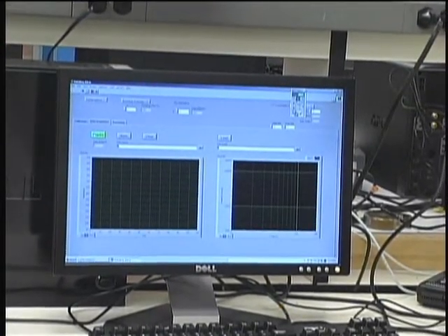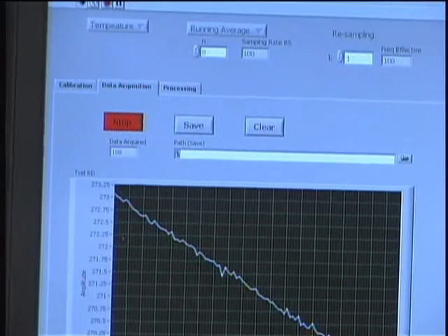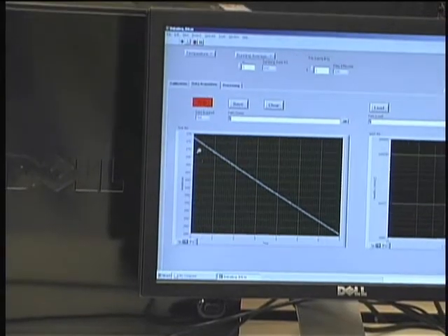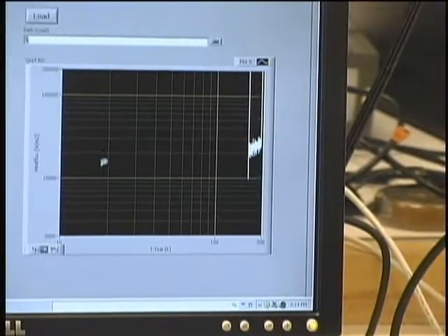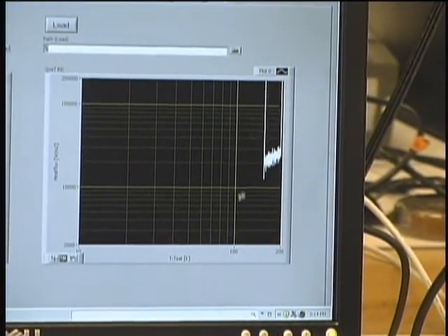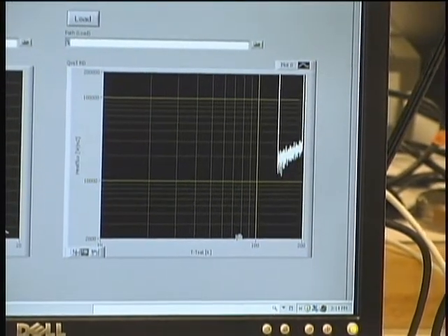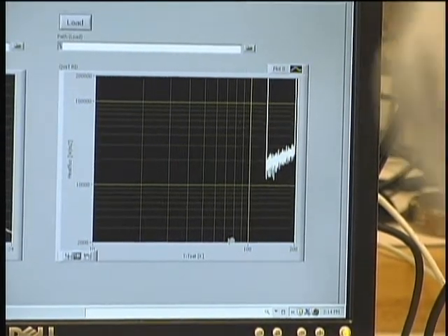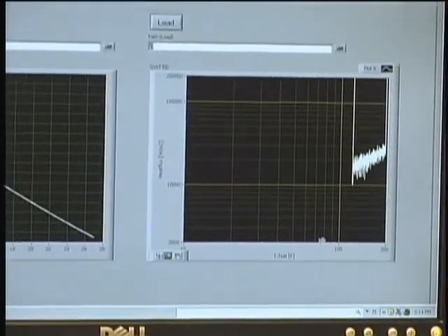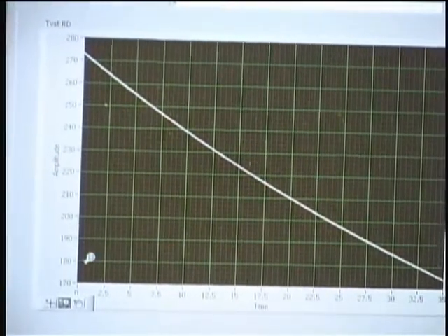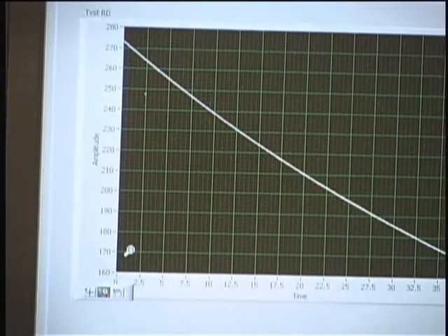There's a tab here called Acquire. You click it, and then you will see that we have two curves. On the left here is the temperature versus time, and on the right it gives the heat flux versus T minus Tsat. Your data file is going to contain this information, and you'll be asked to actually analyze the information yourself. As you can see from the left-hand side, this is the most critical part of the information: the temperature of the copper sphere is decreasing from room temperature very quickly, trying to reach equilibrium with the liquid nitrogen.